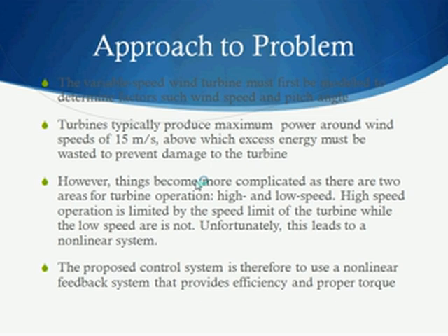Well, in this country, most of the power is stored when hydroelectric plants pump water uphill to store it as potential energy. That's a very interesting idea, because what you're doing is creating potential energy and then converting it back to kinetic energy. Windmills hardly ever do that. But I see no reason why you can't take a wind farm and couple it with a water tower or a reservoir. Yeah, that's true. And so, at some level, if you're thinking about pumping water with your wind turbine, you almost don't need an electric generator in the wind turbine. Right, what you really need is a water pump.